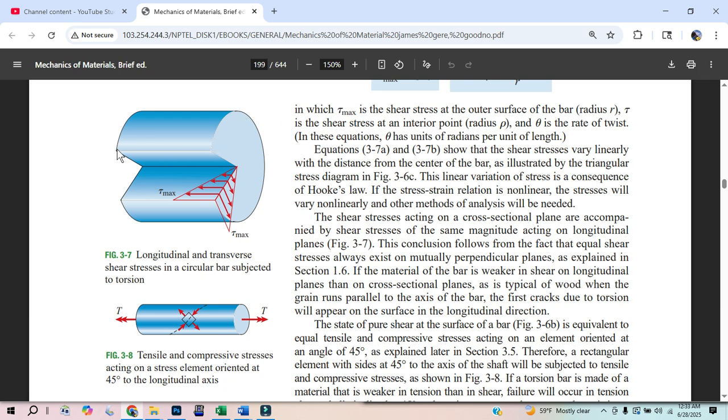I'm going to say, hey, this is fixed to the wall, welded, and now this line became this line. All those discs are doing the same thing homogeneously. We get a linear relationship. So therefore, if this circumferential distance is that, I use that radians times radius is arc length. I know the arc length. I know the radius. So I'm going to do radians times radius is arc length. I want to know radians, which is arc length divided by the radius.